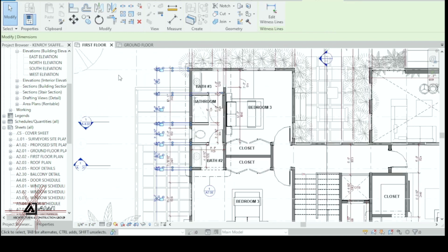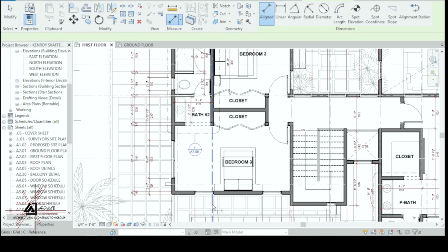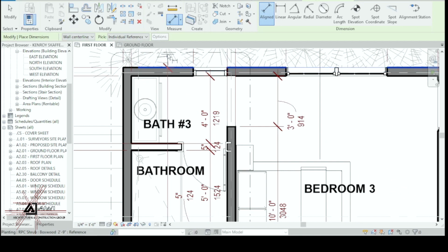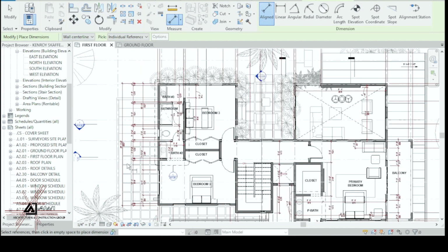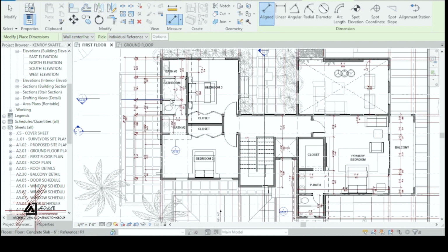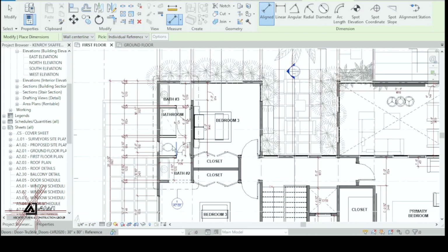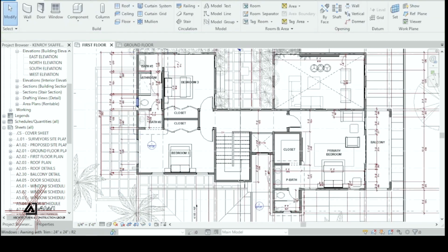And the other line now, I'm gonna put overall dimension, right? So the rule still applies. So I'm going all the way up here, and I'm showing an overall dimension, right? So the person knows that from here to here is 29 feet 3.5 inches, right? That's due to rendering and small walls adding up, right? So first line, openings, right? Second line, walls. Third line, overall dimension.